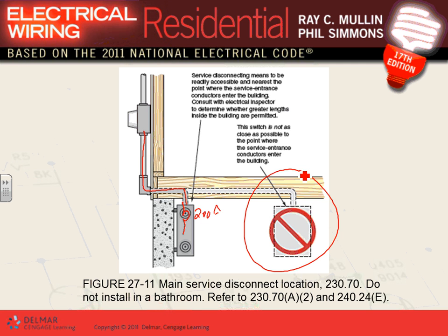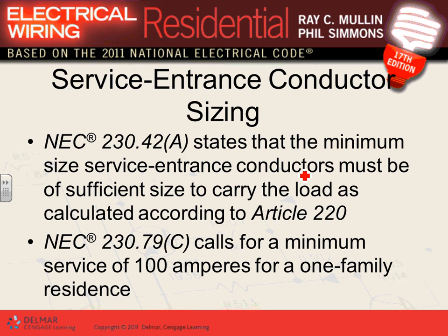Can I get you guys to understand that concept? It is so important. In commercial buildings, guys, the way we solve the problem is we go underground. If we want to put them on that wall, you bring them underground in ducts so they are not inside the building. You poke through the concrete and come up, then you can put them wherever you want. But you can't put them overhead in a conduit. If conductors are underground under the building, they are not in the building. If there's a fire inside the conduits underground, it's not going to burn the building. It's bad news though, but it's not going to burn the building. I can't emphasize this concept enough, guys.